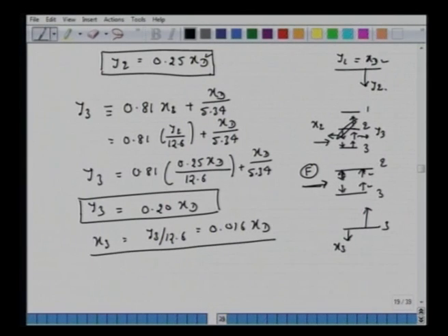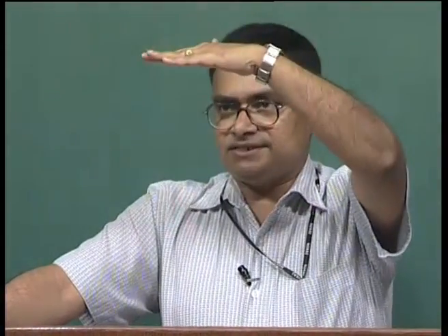So let's try to understand what we're doing here. Again, let's discuss it. We have this feed which enters between stage 2 and stage 3. Now this is a mixing zone, okay, and we made use of energy balance. If you recall, we had the total balance F what enters and two streams L and L bar, and we have G and G bar. So we wrote down this. Go back to your lecture notes. We wrote down this overall material balance, and then we wrote down this energy balance, or the enthalpy of all the 5 streams, 2 liquid and 2 vapor streams with the feed here. Okay, then we got this Q line.